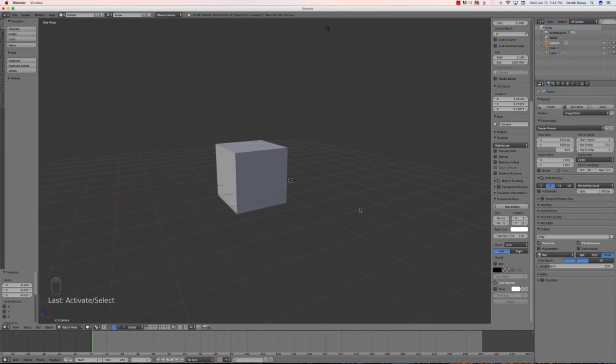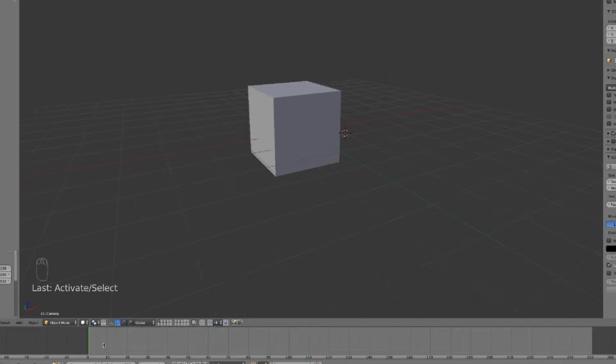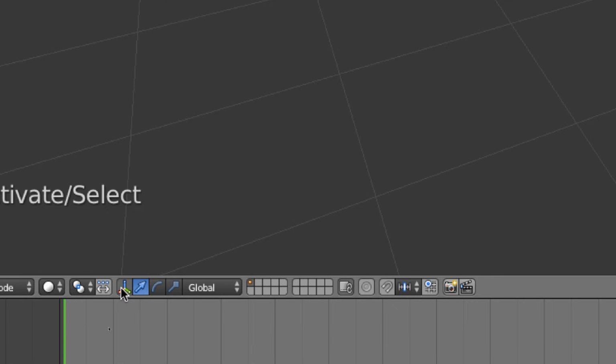You're going to be able to both show and hide your properties. This is the properties panel right here by pressing N. So there, that's on and that's off. This is the tool menu. You'll be able to turn that on and off by just pressing the T key. Down here you will see some different operations that you're going to be able to pull off, and we're going to be able to move with this arrow here. You're going to go and rotate an object with this one and scale with that one.